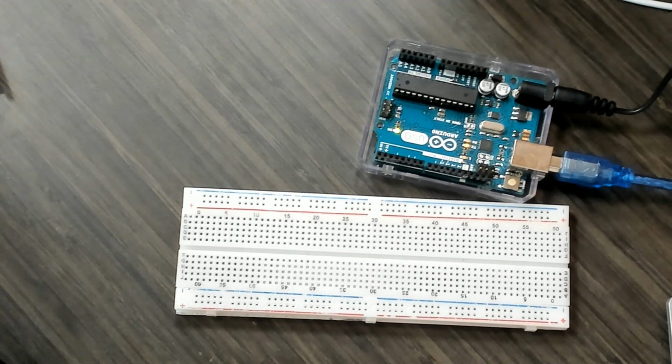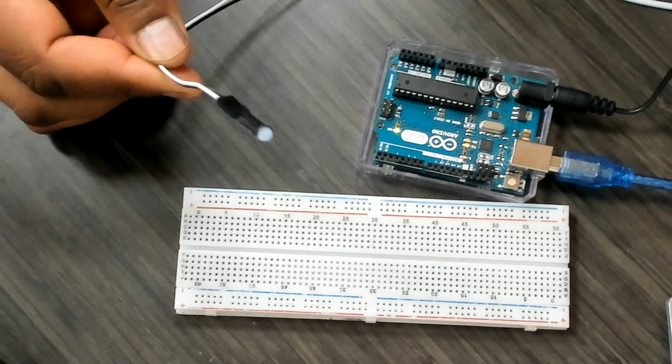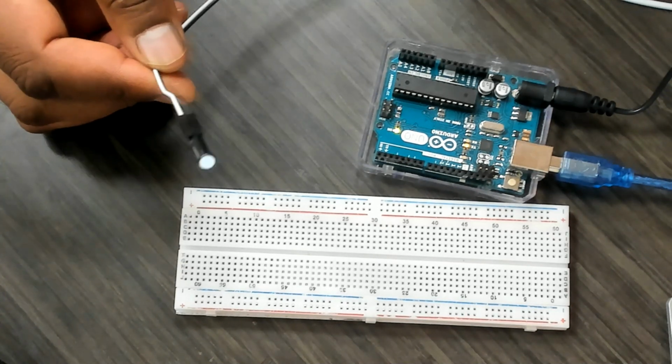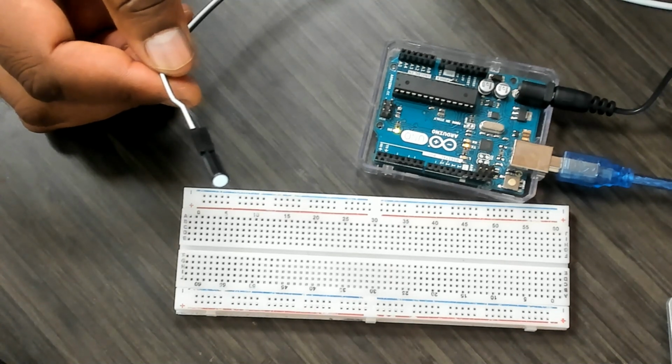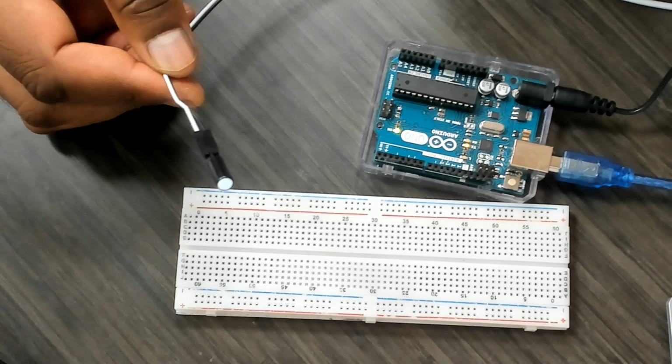But we didn't talk about a pull-up or a pull-down resistor. You should not leave a pin hanging, because when you try to read, there might be a lot of other things going on. It should either be connected to 5 volts or 0 volts. A sensor like this will open a circuit, but it will not connect it to ground. So we will use a resistor, and either pull up to 5 volts or pull down to ground, and then keep it in that state.